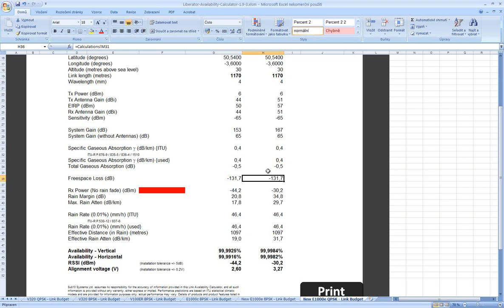It means that now it's working, but you have 6 dB or 3 dB margin, and you are sure that after 5 years, when the receiver will not be so good and the transmitter a little bit lower, the link will still work. Don't worry if you see a better value. You are a good guy, because you have more budget.